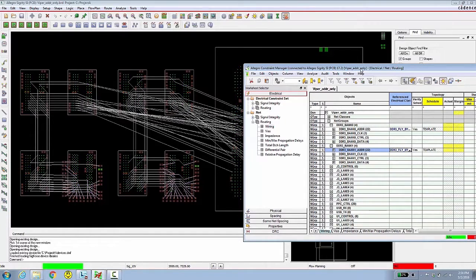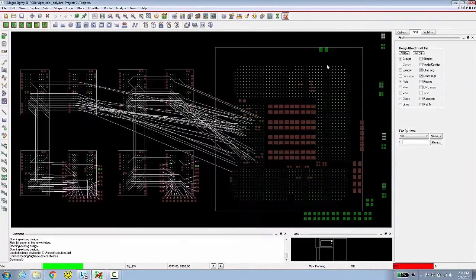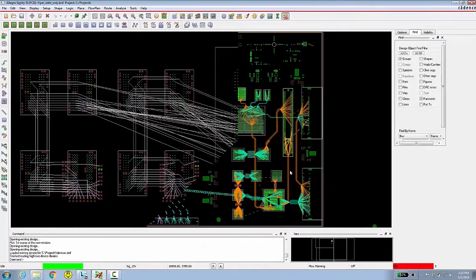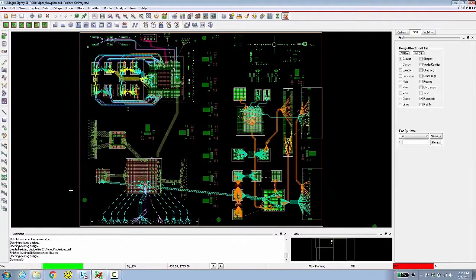Let's fast forward a little bit and take a look at the design after flow planning is finished. This certainly gives a better sense of how all the major routing will take place. The appearance of the bundles is different based on several factors. Coloring can indicate a default bundle, or one where the etch is limited to a specific layer. In other cases, a bundle with a crosshatch or dashed appearance was auto-generated based on net groups in the design, whereas solid-colored bundles were generated manually.